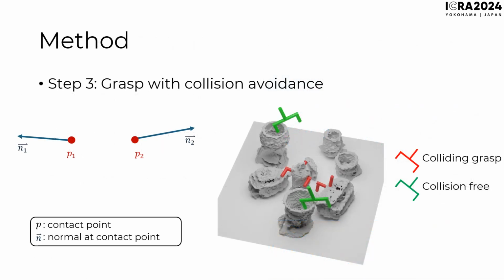After we obtain geometric estimates, we generate a collision-free grasp. We do not use anything fancy, but found the grasp position using a simple heuristic on contact points and normals. Also, we adapted the existing planning library in PyBullet to plan the trajectory.